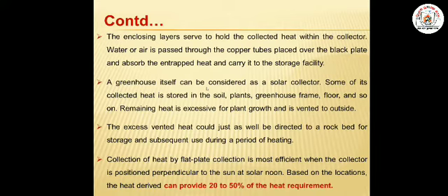A greenhouse itself can be considered as a solar collector. Some of its collected heat is stored in the soil, plants, greenhouse frame, floor, and so on. The remaining heat is excessive for plant growth and is vented to the outside of the structure. Here, the excess vented heat could just as well be directed to a rock bed for storage and subsequent use during the period of heating.